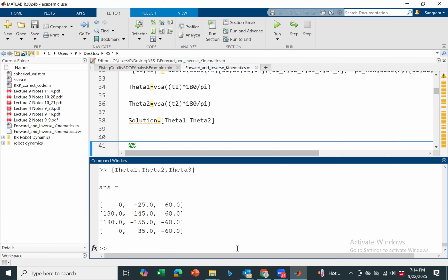You can achieve the same px, py, pz with these three angles, or with these angles, or these angles, and these angles. So what is the right angle? Many times what you do is perform something called workspace analysis, which means finding the most feasible joint angles, and then you pick the right angle.